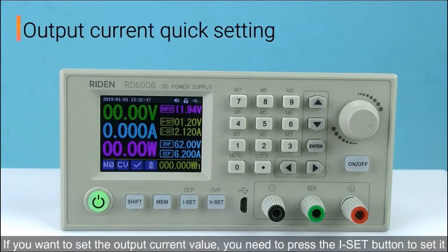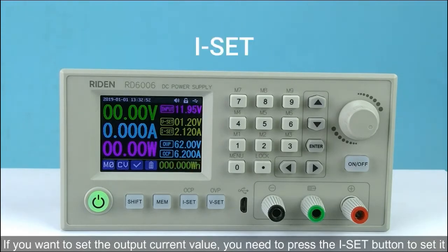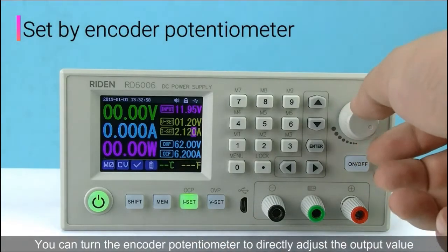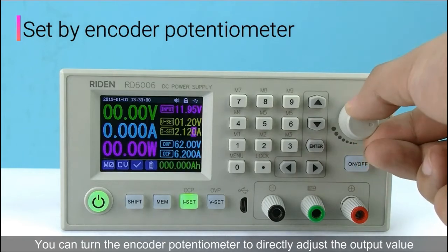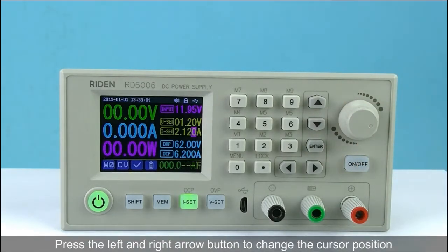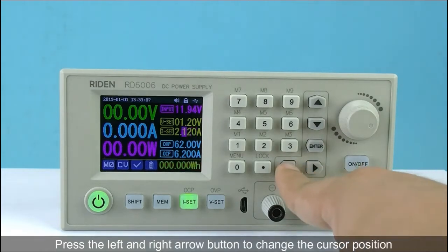If you want to set the output current value, you need to press the iSet to set it. You can turn the encoder potentiometer to directly adjust the output value. Press the left and right arrow button to change the cursor position.